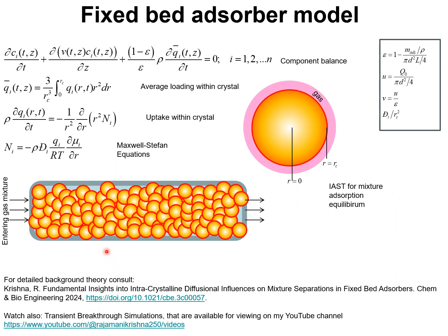Suffice it to say that the use of the Maxwell-Stefan relations for describing intracrystalline diffusion is of vital importance for kinetic separations. Simplified approaches such as the LDF model will not work for kinetic separations, but I will discuss that in other video presentations.